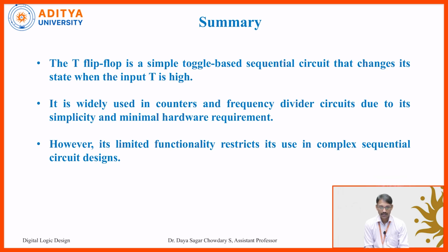Coming to the summary, the T flip-flop is a simple toggle-based sequential circuit that changes its state when the input T is high. It is widely used in counters and frequency divider circuits due to its simplicity and minimal hardware requirement. However, its limited functionality restricts its use in complex sequential circuit designs.